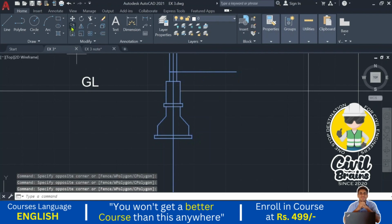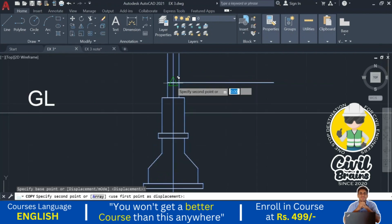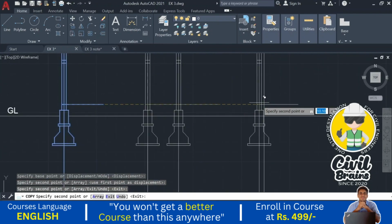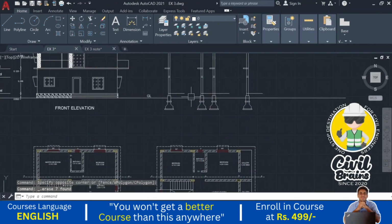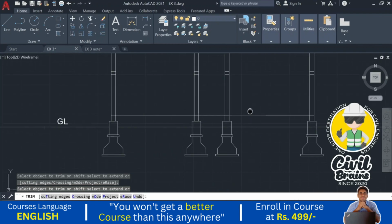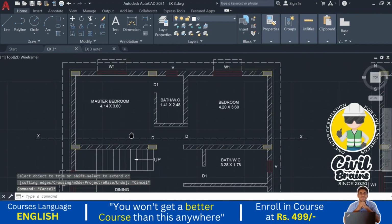I just use the copy command, and I just consider the center point of this wall as a reference point and just copy here. I just on the ortho also. I just copy. I just delete this one, and I just extend the floor plinth level first from here to here, and I just trim the extra part. So now we just come here. So one wall we have cut it.